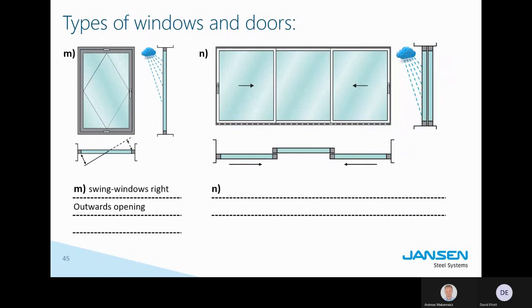An interesting opening type, quite popular, especially with Arte 2.0 and Arte 66. This is what the customers go for. Horizontal sliding window. We have several systems here on Janisol and Arte and Economy. So just a slider. The gasket here is a brush gasket in the bottom. The only downside of this type of window is quite low performance when it comes to wind load and air permeability.